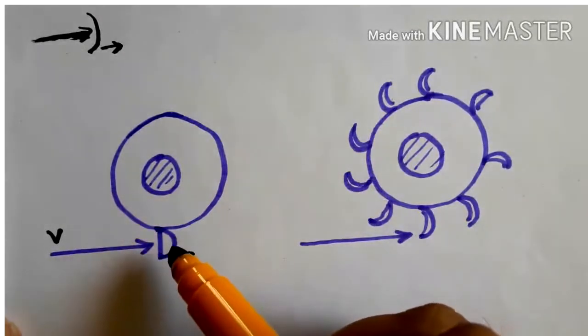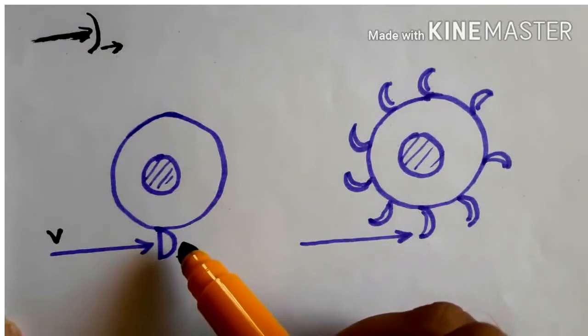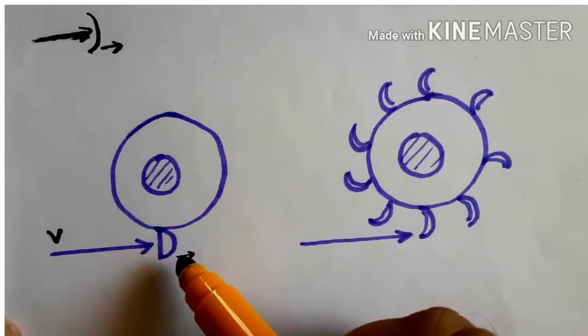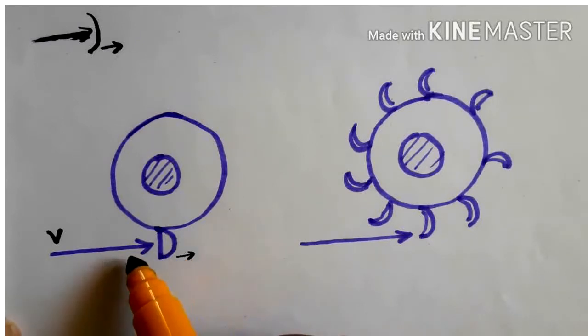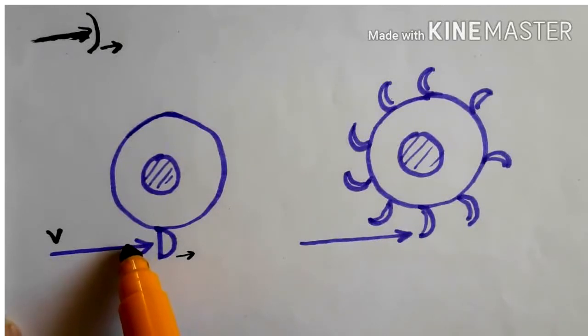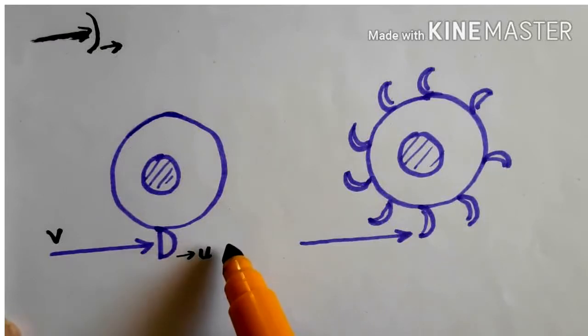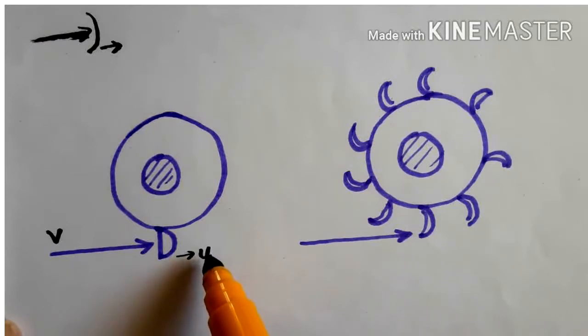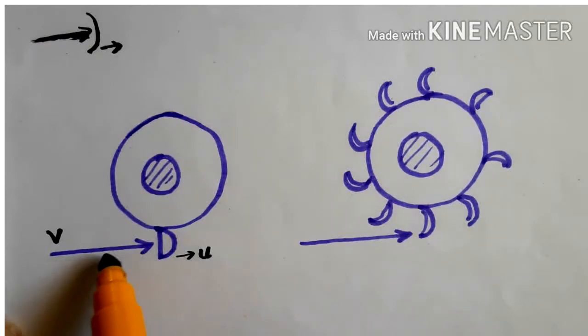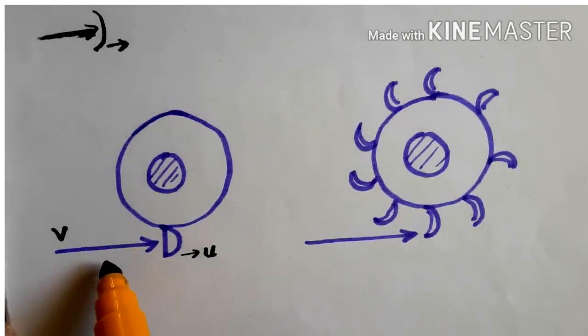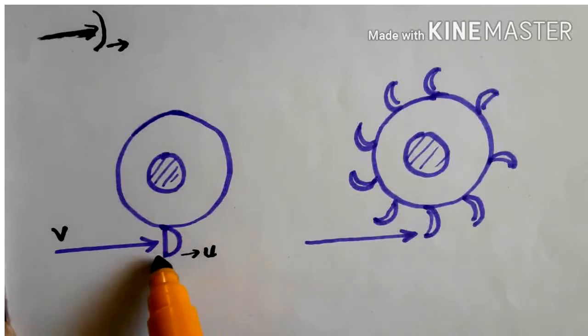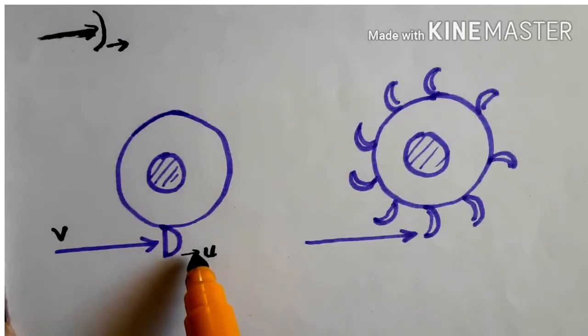This case is only a theoretical case, because in this case the distance between the plate and the nozzle, that is the nozzle provided for the jet, will be constantly increasing at the rate of u per second, which in turn would require continuous lengthening of the jet at this rate in order to strike the plate.